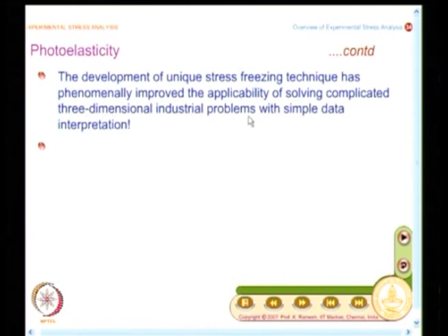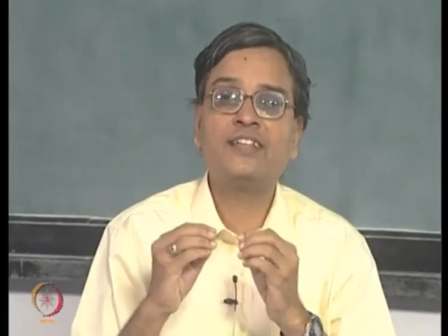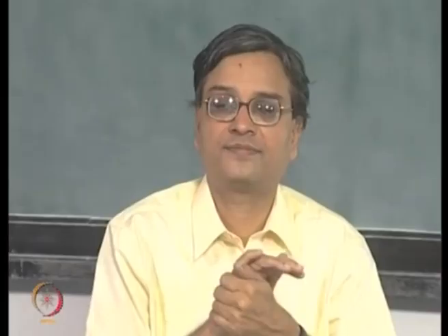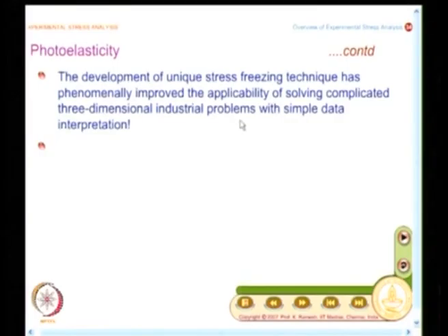Analyzing the problem as a whole is very difficult, and what you do here is you take the advantage of analyzing the problem as a whole. At the same time, from the analysis point of view, you still live in 2 dimensions by slicing the model into thin slices. So, many industrial problems, whatever engines you see across, whatever nuclear reactors you come across, have all gone through mandatory 3-dimensional photoelastic analysis.